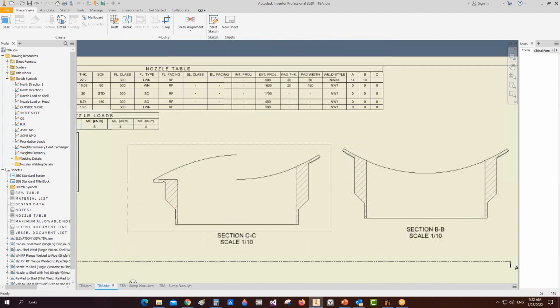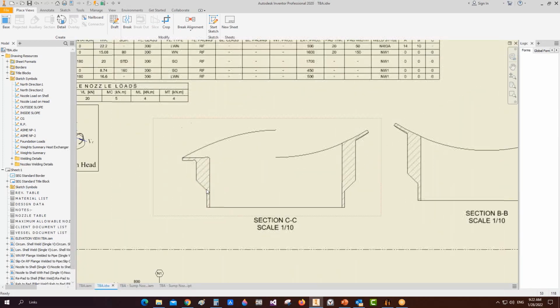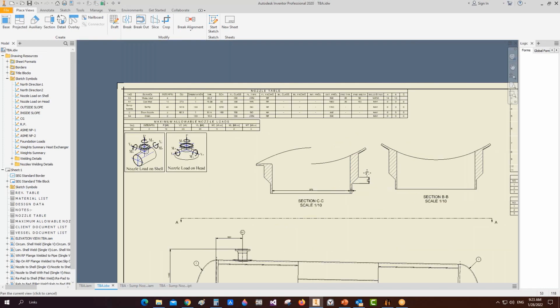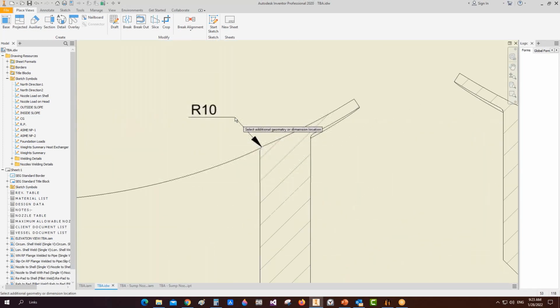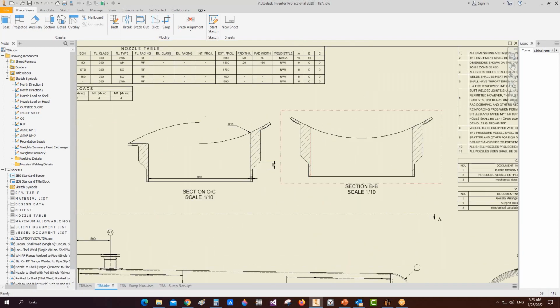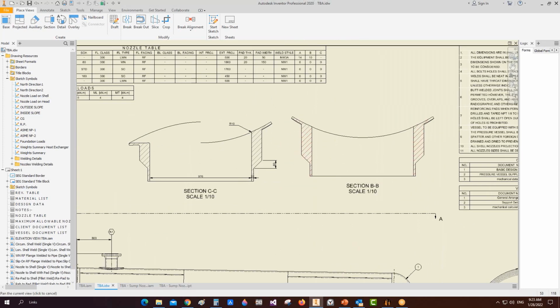So you can add the dimensions on this hub like that, the thickness, the hub height, the hub length, the bevel height, all of that. Define the radiuses here and modify it from the 3D model. So many different options you can make if you would like to make a separate detail like this.